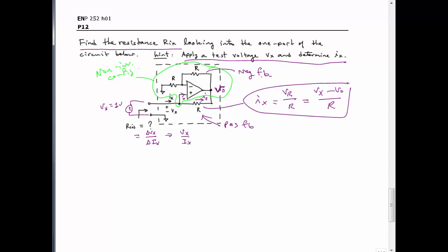Now, what makes it particularly true in this case, R is not grounded. That's what we've looked at before. In this case, R is connected back to the non-inverting input. And so you might argue, well, if VO changes, that positive feedback resistor could change the voltage at the non-inverting input, and that in turn would change the output. And that's very true.